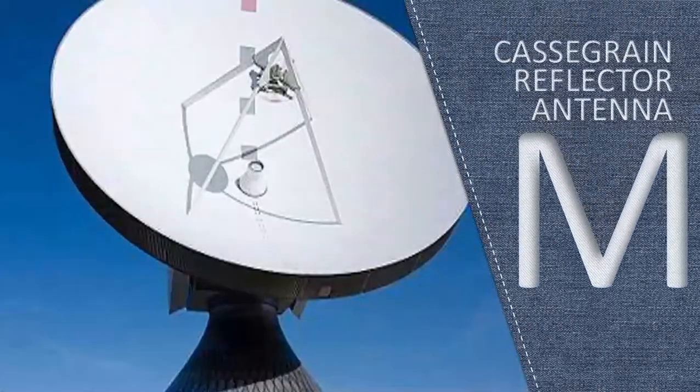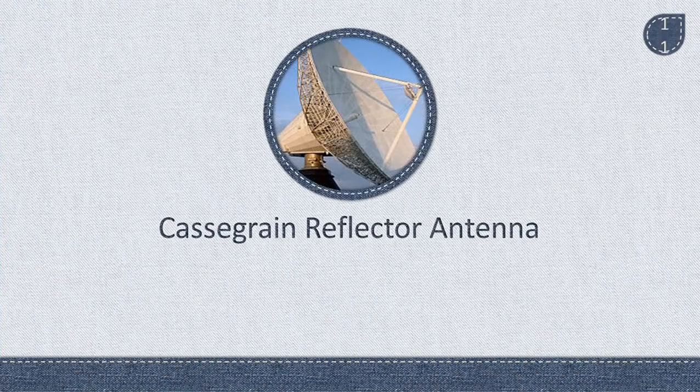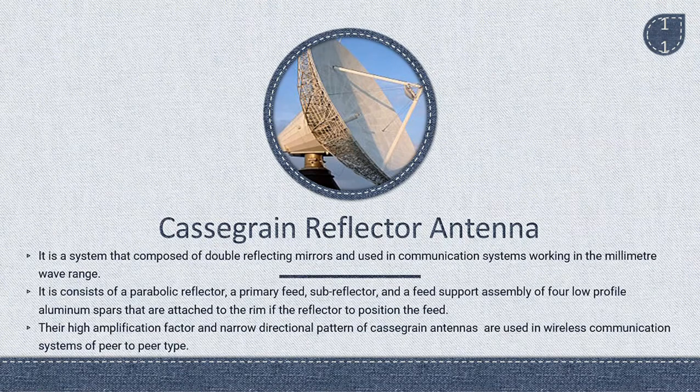Next is the Cassegrain Reflector antenna. A Cassegrain reflector antenna is a system composed of double reflecting mirrors and used in communication systems working in the millimeter wave range. It consists of a parabolic reflector, a primary feed subreflector, and a feed support assembly of 4 low-profile aluminum spars that are attached to the rim of the reflector to position the feed.